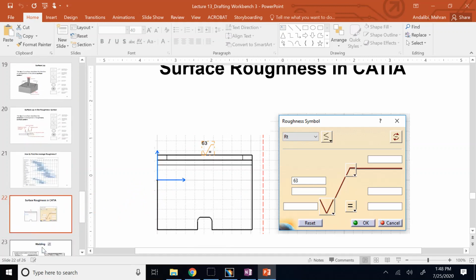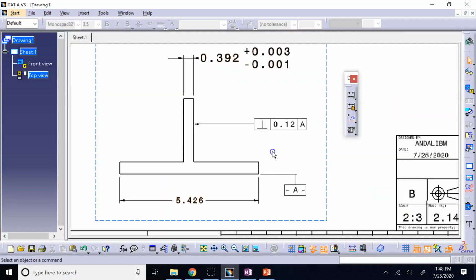How do we show surface finish in CATIA? Let me show you. If I say this surface sits on something, provide an average of 40 microinches roughness height, with a parallel lay or with a perpendicular lay, how do you show it on the surface? The surface finish is not in the dimension toolbar. It is actually in the annotation toolbar, and that's this one between T and table.